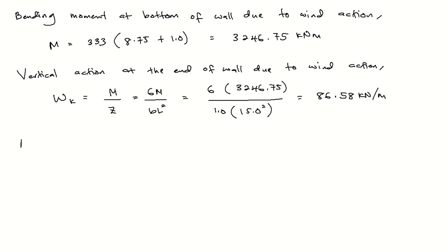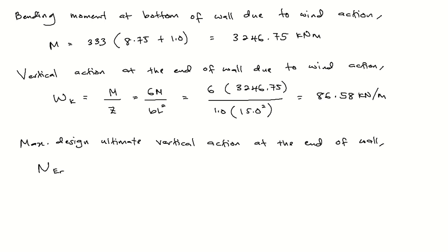So maximum design ultimate vertical action at the end of wall. Okay, NED max is equals to 1.35 GK plus 1.5 QK plus WK.